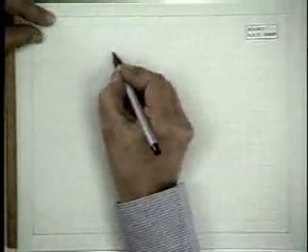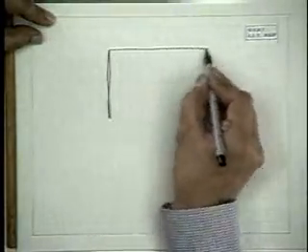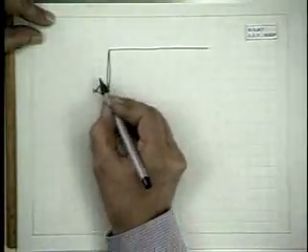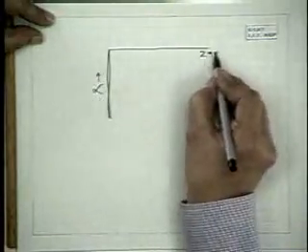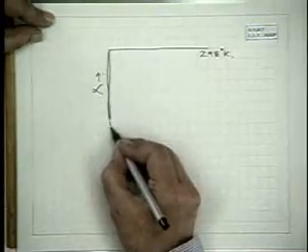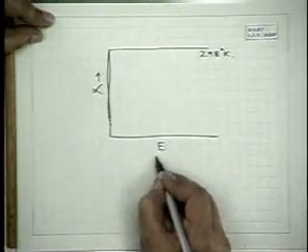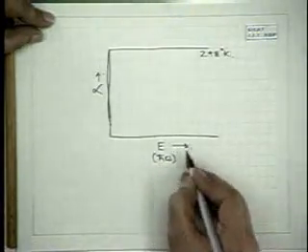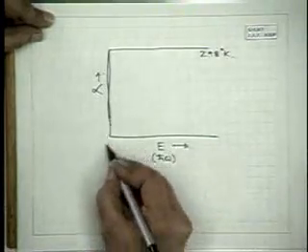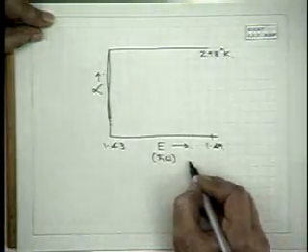Now if you look at the optical absorption as a function of the electric field, we find quite remarkable changes. At 298K, when you have no field, this is h cross omega, the photon energy, 1.43 to 1.49 for gallium arsenide.